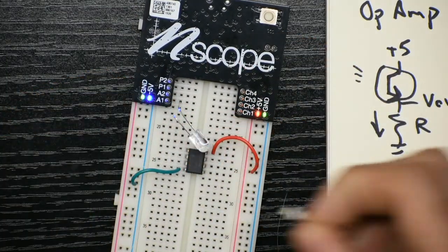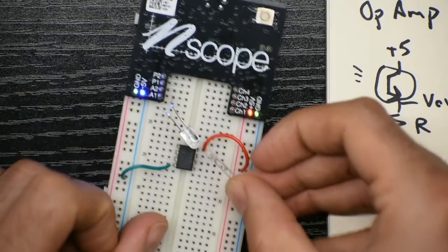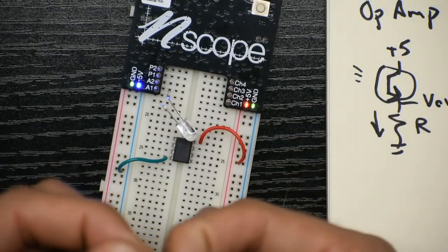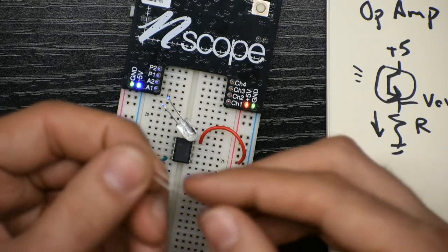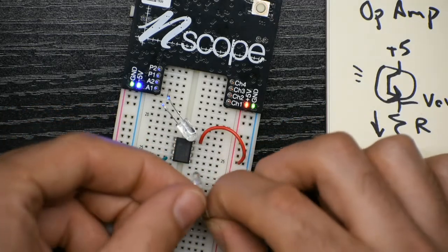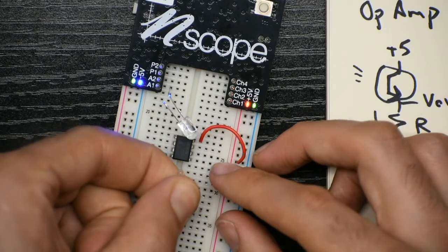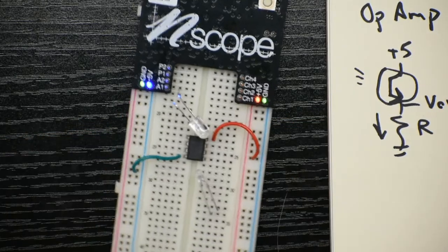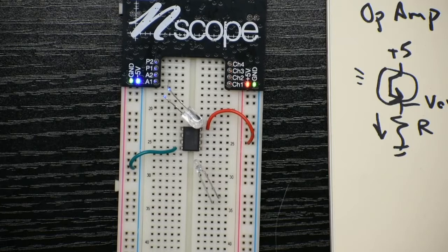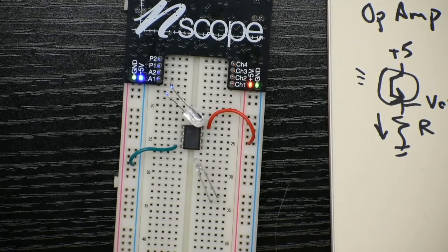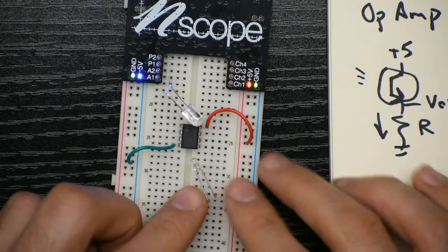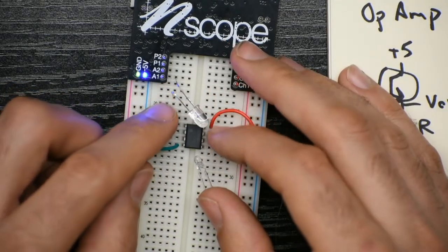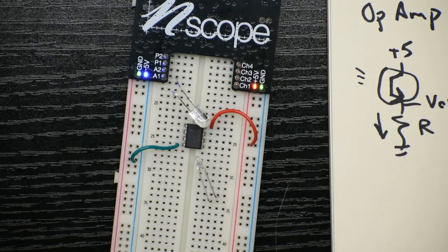And then my phototransistor, I need that to point at the LED. So I'm going to take that and bend it at around the same height. And remember, the long side is the negative side for the phototransistor. So I'm just going to build that somewhere on my breadboard. And I will need to apply 5 volts to my phototransistor and give it a resistor to ground, and I need a resistor to ground for my super bright LED.